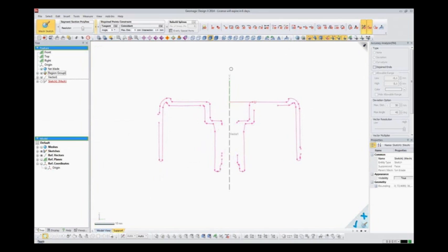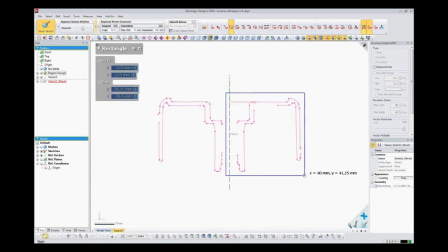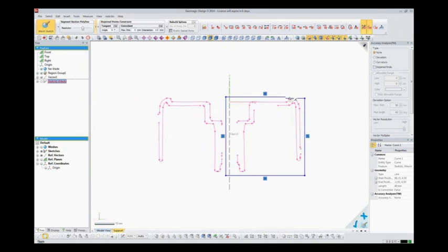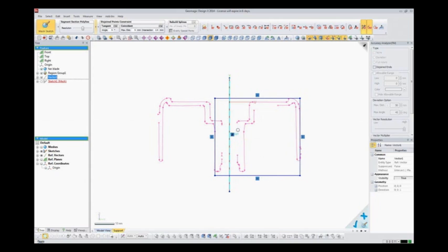And now a top-down construction is quite easy. I'm just doing boxes, just simple boxes, and snap them on this area. Leave that a little bit over the center because we will trim everything at the center line. I'm getting my center line into the sketch, making it a construction line, and then use the power trim function to trim off the remaining part.